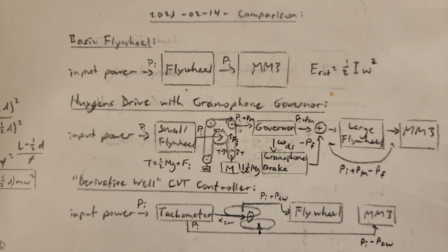The problem was that with your current setup, you are trying to keep the mass at a constant height. What that means is that it's not actually moving, and if it's not moving, it cannot do work and thus cannot apply power. Why is that? Because work is equal to force times distance, or power is equal to force times velocity. So if this mass is not moving, then that means that you're actually not achieving your goal whatsoever.